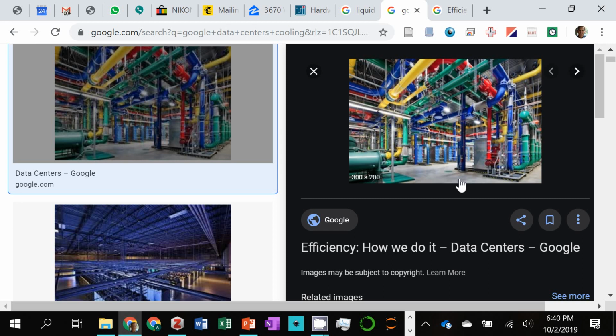All right. So it all comes down to the lattice scattering, right? If you don't keep the semiconductor operating at the right temperature, you're going to increase your resistances a lot, and that's going to mess everything up. When you laid out your transistors on your chip, you said, okay, this one's going to have this resistance, this one's going to have this resistance. If all of a sudden all your resistances in your 1 billion transistor system double or triple, then you're done.